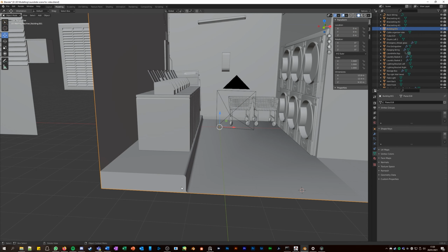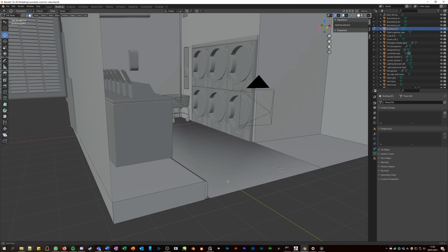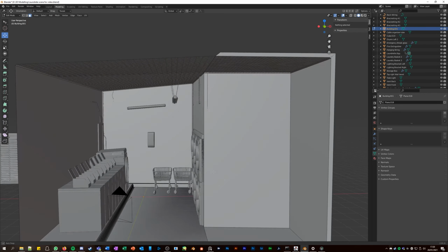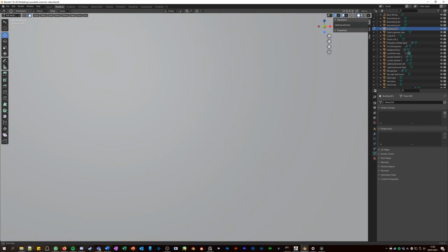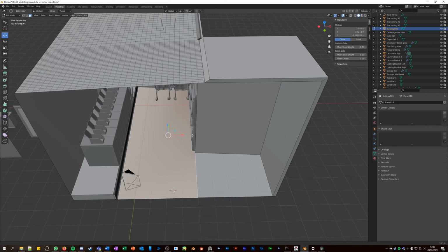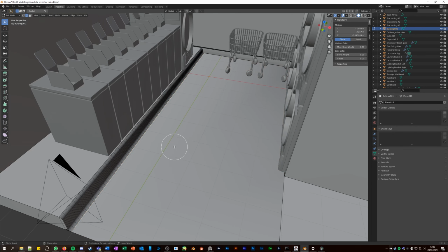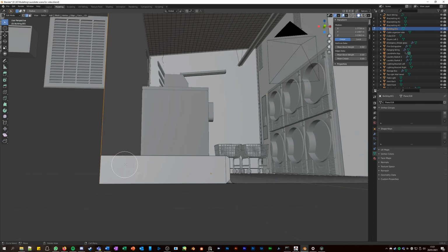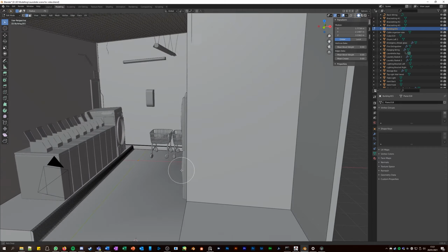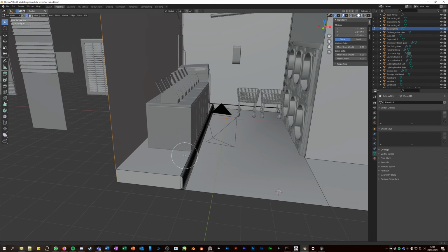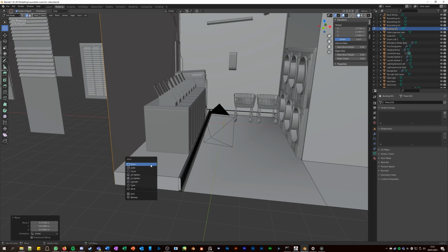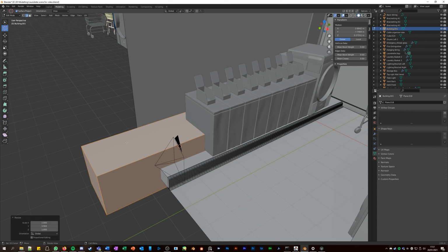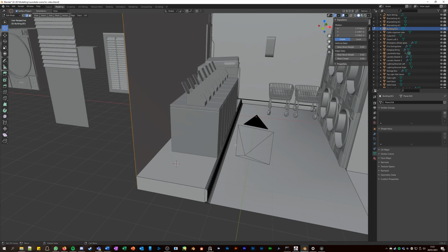However, in doing this, I came up with a bit of a problem. Because I extruded this up and extruded this to the side, it messed up with the geometry of it. So not everything's square. This floor is made up, this side has multiple edges to it. And then this edge too, nothing's perfectly square, and then this line, if I select this line, it goes all the way down there, so there's two overlapping lines, which caused some problems later down the line and could have been improved, so I would have used a separate object in this position. I put a cube there and then mapped it along the right path and done it like that in separate objects, as it makes everything fit together easier.